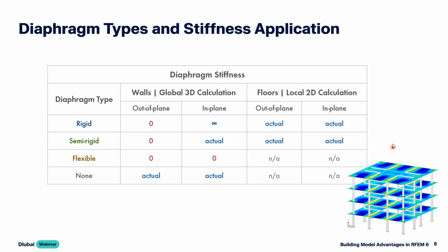So we extract out this model internally for only this single floor. We support it where we have any elements framing in, and we'll go ahead and apply the loads, which end up being gravity loads only. This will make a little bit more sense once we get to our example. So this is purely a gravity load analysis for our floor design. This one, I'm hesitant to say it's only lateral design because we are still applying gravity loads too, but we are applying the simplifications here set forth by the different diaphragms.